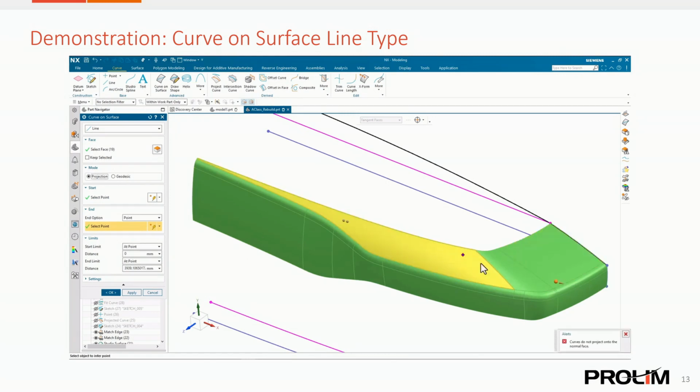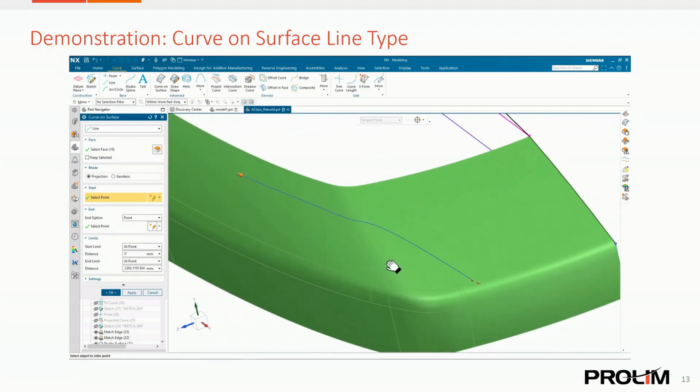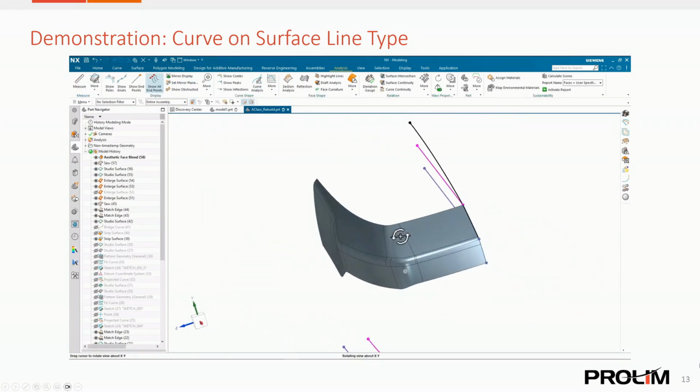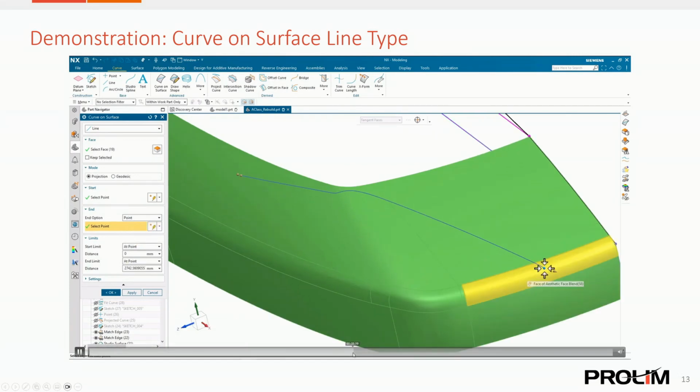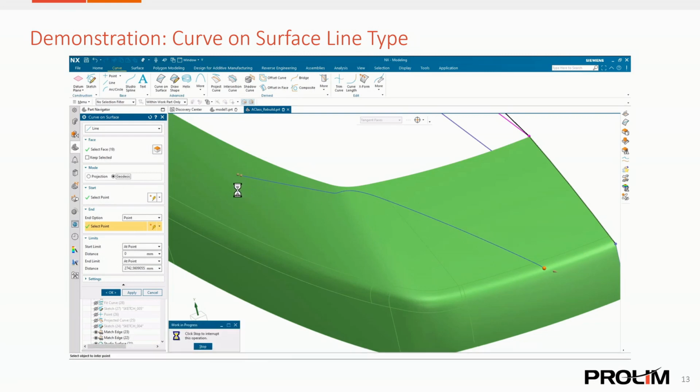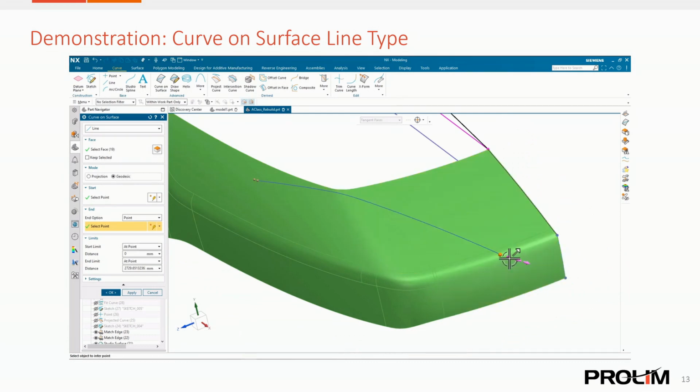So this is just showing the differences between the two and how you can use them, like project a curve can't cross multiple faces like that, whereas geodesic would be able to. So it's just showing you what that difference looks like, and you can clearly see where it rounds up around that edge. And if you change it to geodesic, it'll go ahead and correct that, giving you that minimum arc length. Here's our projection. And you can see as it swaps to geodesic, it'll give you that fine arc length across instead of that projected line. So that's the key distinction there between the two.